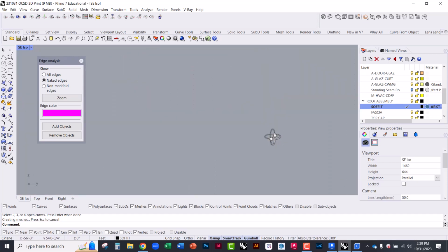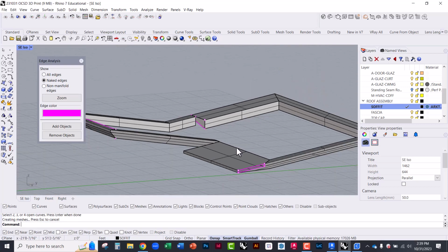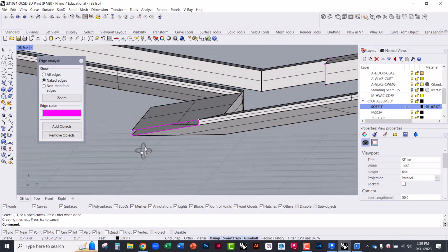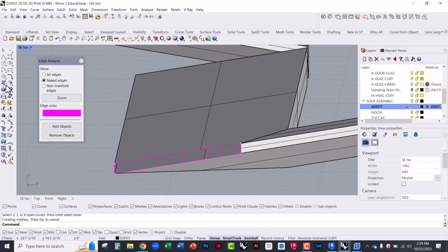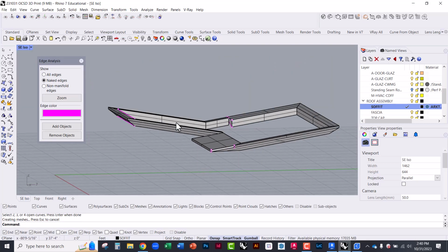Looks like it got confused there, that's not right on the edge. So what I could do is loft. Well, it looks like that's not connecting still. So I'm just going to draw a line and then use this surface from 2, grab that line, select this, enter. And now that I have a surface everywhere, it looks like I'm forgetting this one too. I'm going to go to surface from 2, select both of those, enter. And now this thing should be fully capped and fully watertight.